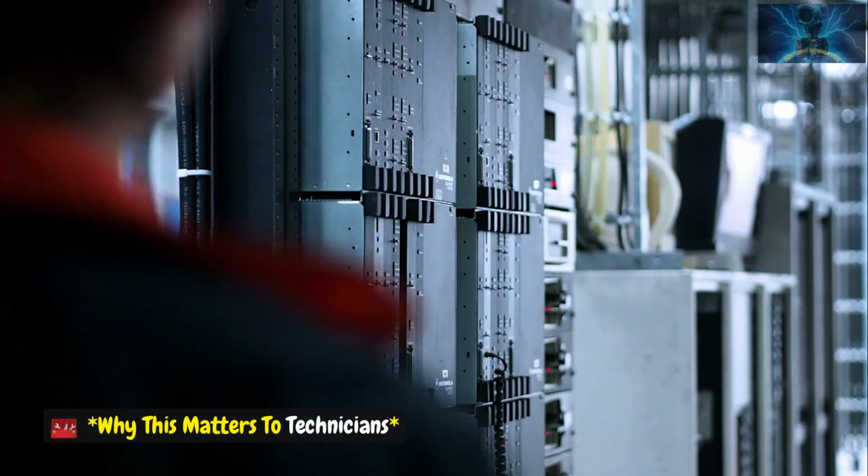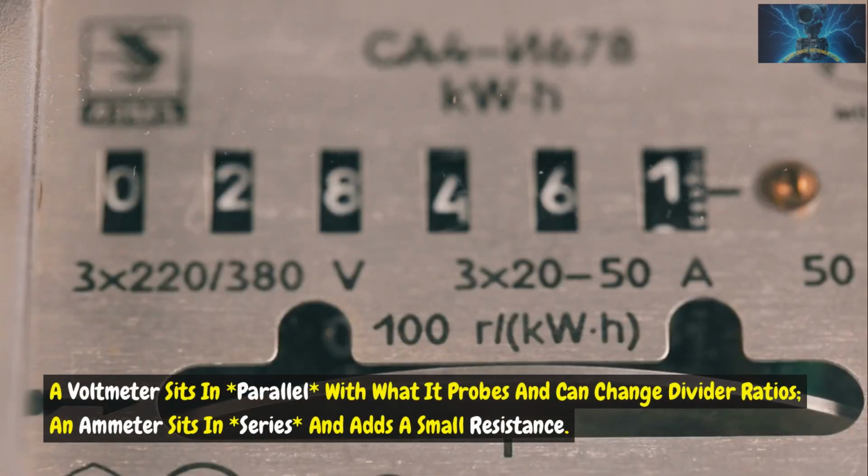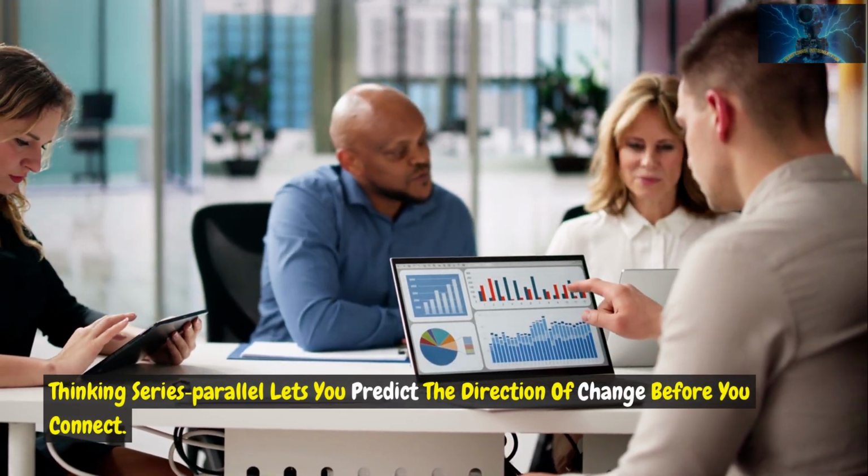Why this matters to technicians: measurements change circuits. A voltmeter sits in parallel with what it probes and can change divider ratios. An ammeter sits in series and adds a small resistance. Thinking series parallel lets you predict the direction of change before you connect.